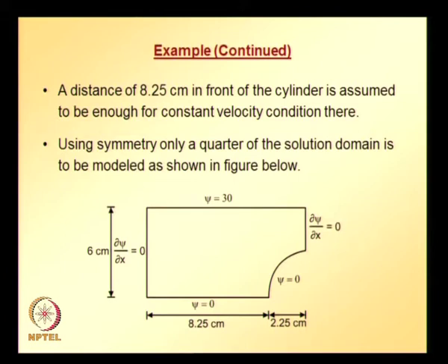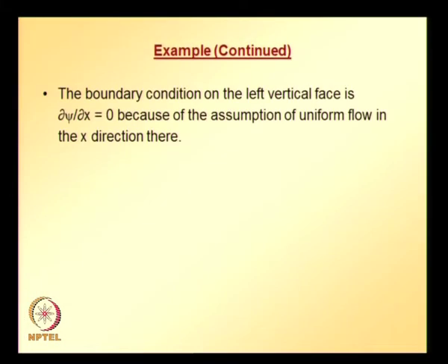So, we need to solve the second order differential equation that we have seen earlier in terms of psi, subjected to these boundary conditions. The boundary condition on the left vertical face is the partial derivative of psi with respect to x equal to 0, because of the assumption of uniform flow in the x direction there.